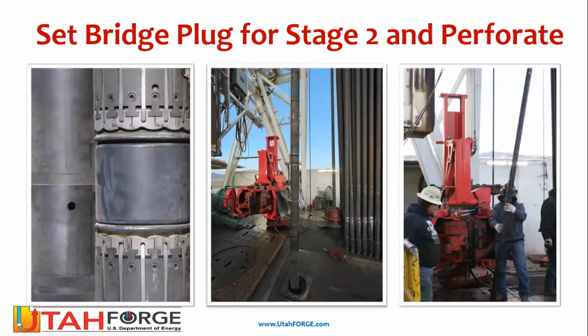After flowing back this particular stage, which was a slick water stage without proppant, we set the interwell bridge plug above that zone. You can see the element itself at the left, and the bridge plug being run in the middle. Then extreme wireline went in with a 20-foot long gun, single cluster.